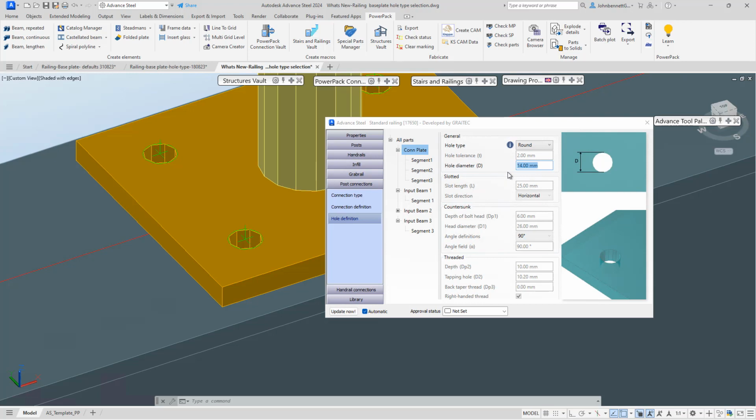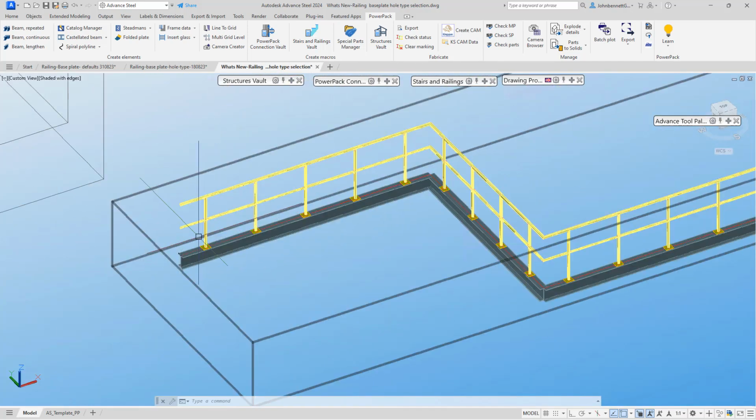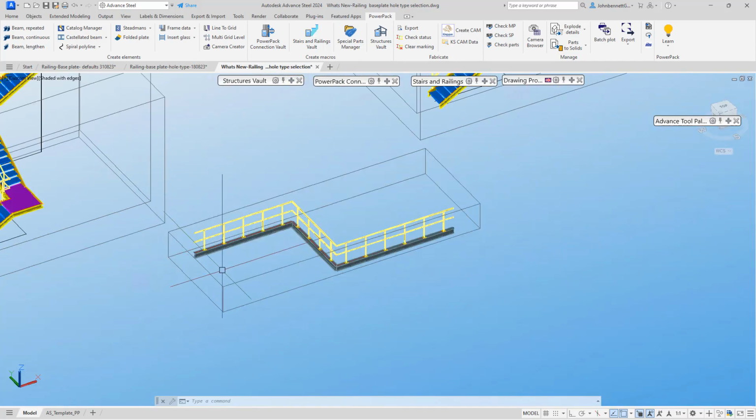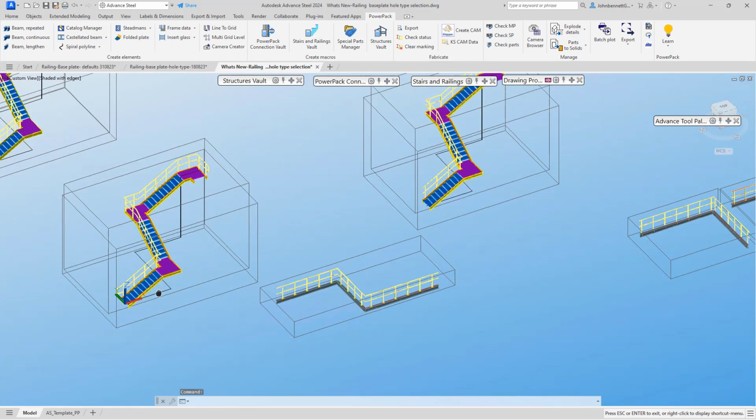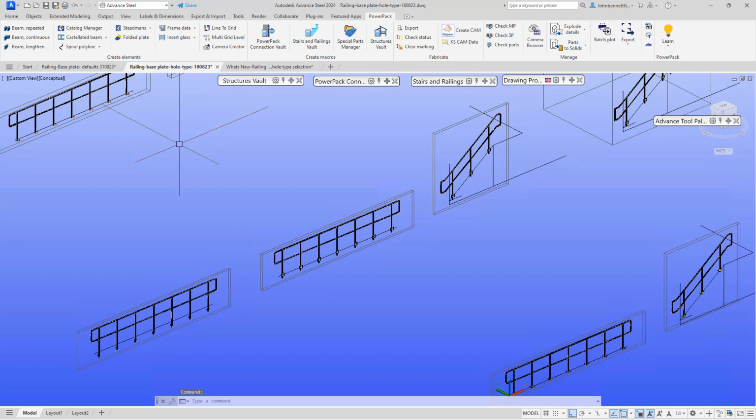Round hole is actually the same in this condition. If the bolt default was set to something different, if it was set to countersunk, when you changed your mind, you might want to change this to round, which is why there is a round field within the dialog. And this does apply to sloped railings, level railings, however you wish to configure your railing arrangements within your staircases or areas, platforms, etc. This change has been made throughout that process for every type of railing, and that's going back to key clamp railing, double post railing, and the standard.